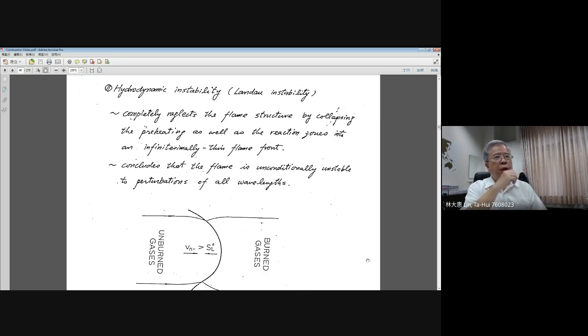Then we shifted a little bit to the transient state for premixed burning, to give you an understanding of the S curve described by the Damköhler number, which we use to identify the conditions for ignition and extinction. Ignition and extinction are transient states for a given premixed burning.